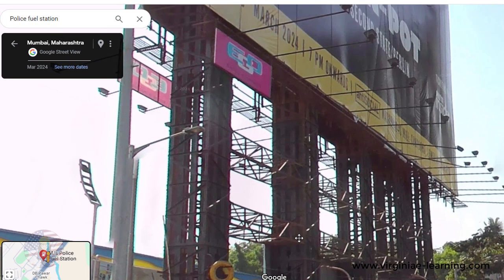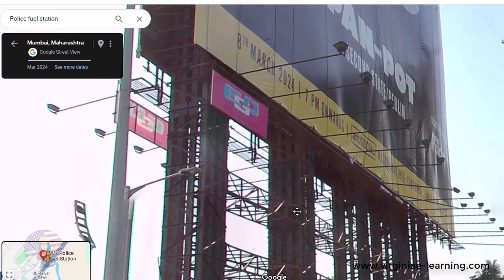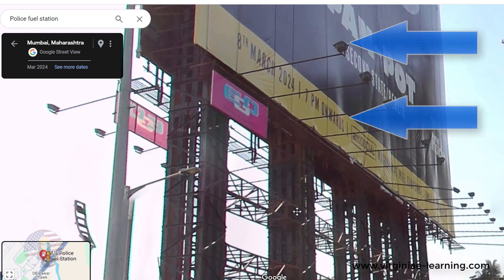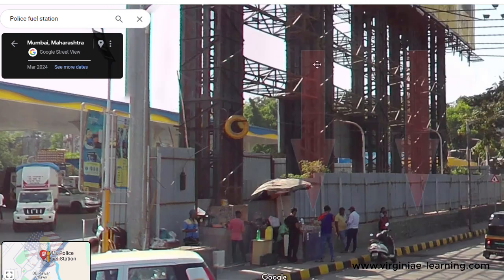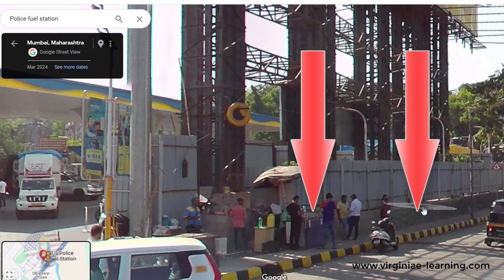However, before we conclude that the hoarding structure was simply too big and incapable of bearing the force produced by the wind, we should understand that whatever loads are present on the upper part of the structure must be compensated through the foundations. In simpler terms, this means having sufficient weight in the foundations, using criteria similar to that used in the design of retaining walls.